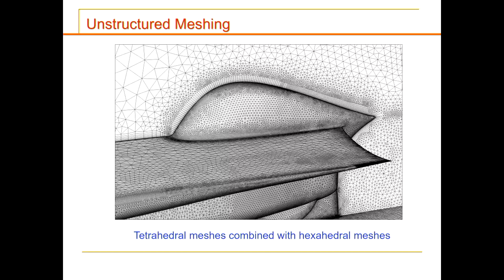But sometimes you have to do a compromise. Okay? Like what you see here is a compromise. This is part of the, I think, the solar car design itself. If you look near the tip of it, you still have a bit of structured meshing, right? You don't have triangular meshing. Why is it so? Because the prismatic meshing is more suitable to resolve the boundary layer at the end of the day, right? So that's why you have a mixed meshing.